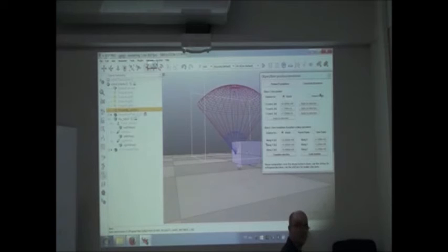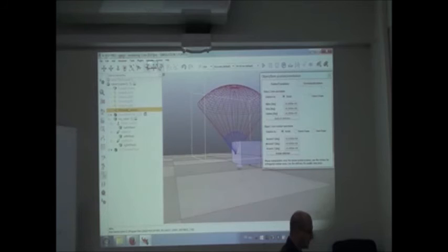Okay? Everybody's okay? Now the rotation. I click, it's the same. If I do that, it will rotate like that. I don't want to rotate like that, I want to rotate in the other direction. So in order to change the rotation, I click control. This is the one I want. But if I wanted another one, I need to click another time. Release and click. If you click and release, it will change the angle of rotation. And then you can rotate it 90 degrees.